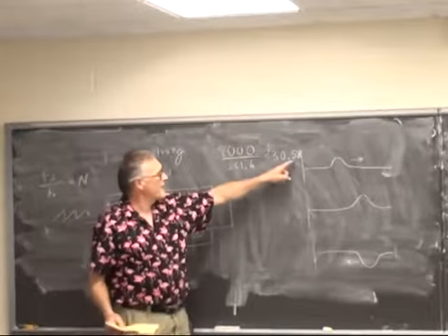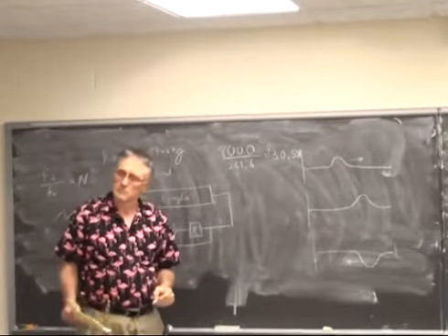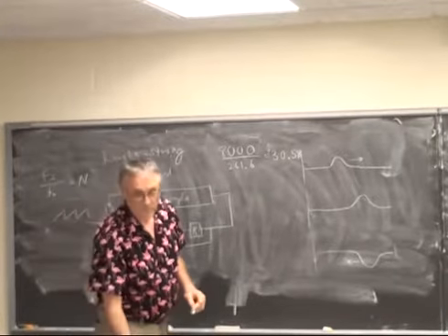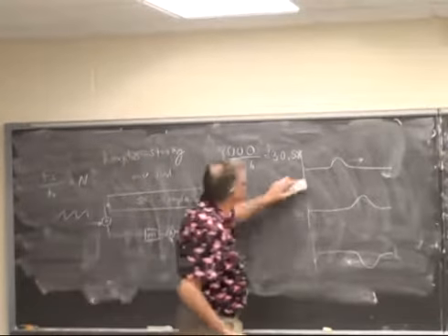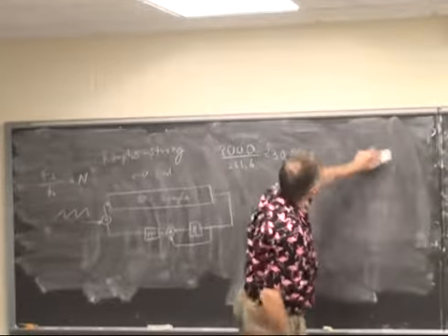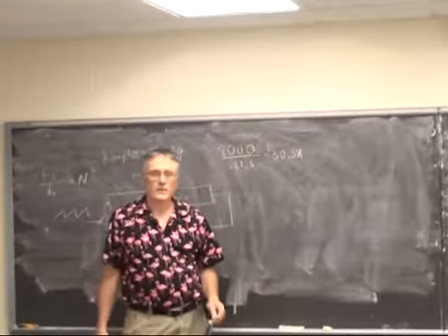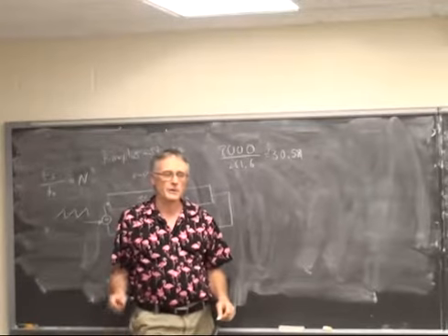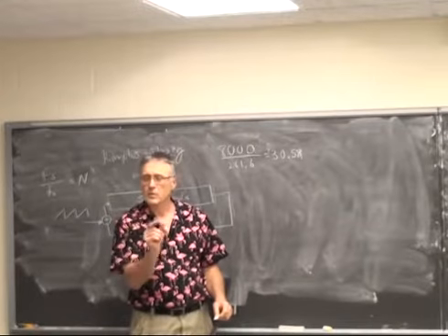How do you make a half of a shift register step? Any ideas? Well, it depends on a DSP trick. You make a phase shifter. You make a DSP module that has a phase shift between 0 and 1 sample.